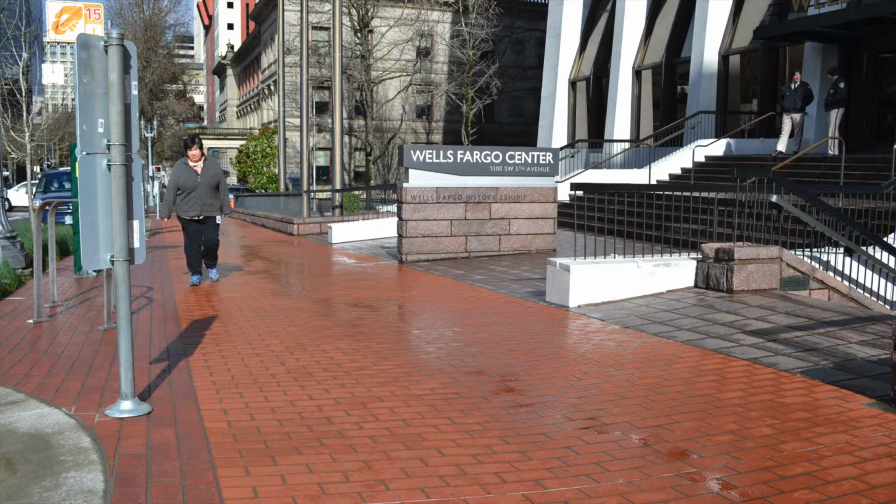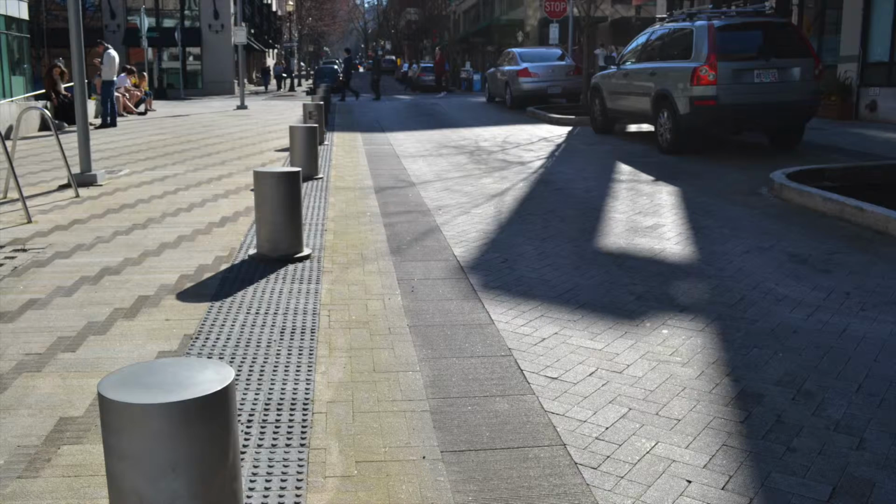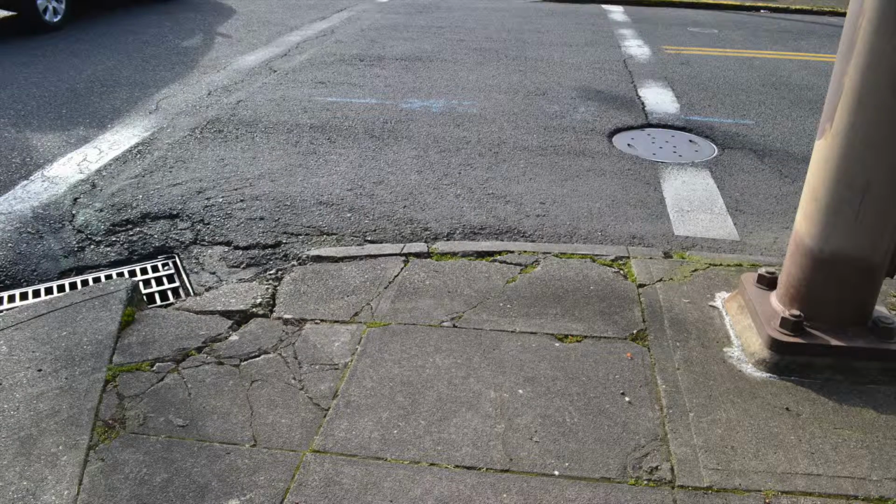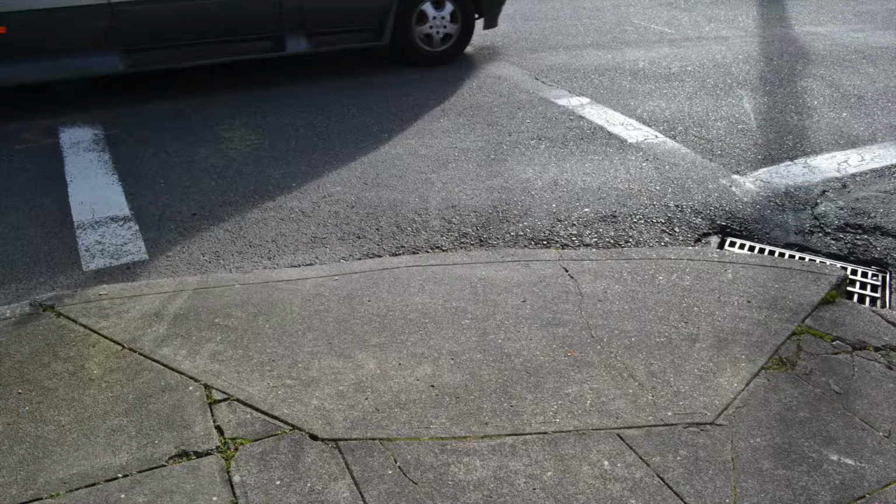Accessible route. A change in ground surface, color, or pattern can alert an individual to the edge of the path of travel, entrances, or other transitions. The path of travel from parking to the facility needs to be accessible. Here's an example of the lack of a curb cut in the direction of travel, forcing the use of a curb cut into oncoming traffic.